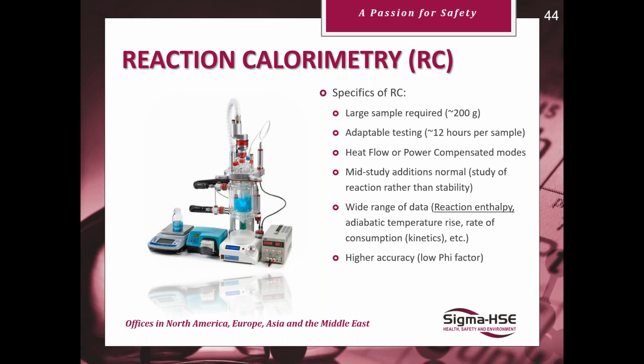So reaction calorimetry, typically a large sample, so in the order of about 200 grams. We need that kind of higher amount to make sure that we've got thermocouples and stirrers fully submersed, so it's all working correctly. Adaptable testing, so they can be sort of 8 hours to greater than 12 hours. It really depends on the reaction under study.